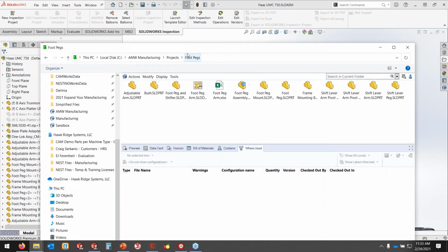Yeah, I do have a question really quick, Daniel. Sure. Samuel was asking me, is there a way to set up a pattern? So every time I right click and I say sort tools and I have to drag and drop, can I make a scheme in there beforehand? Yes. Yeah, I answered that question already. So you can actually set the schemes in the database, and they'll come into that lower right-hand side window when you're in the saw operations dialog. There's a little drop-down where you can select multiple different schemes.